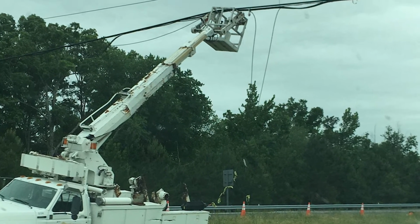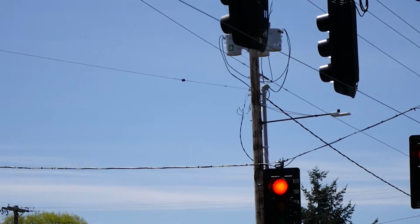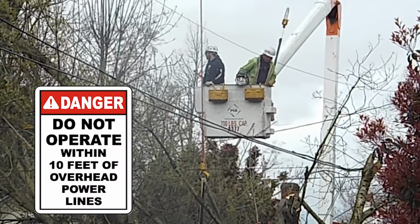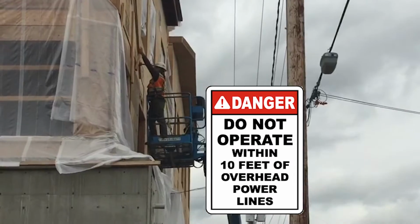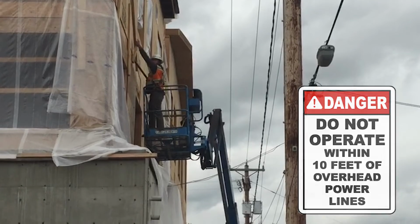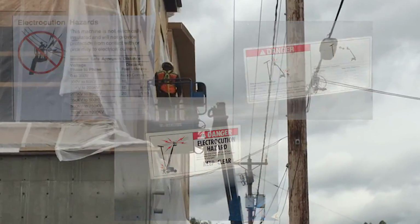Electrocution is a common cause of aerial lift operator fatalities. Operators must take care to identify, and avoid, sources of electricity. Operators must maintain a distance of at least 10 feet from any live source of electricity up to 50,000 volts. For every additional 10,000 volts, add an extra 4 inches of minimum clearance. The aerial device will be clearly marked with minimum safe clearance distances.